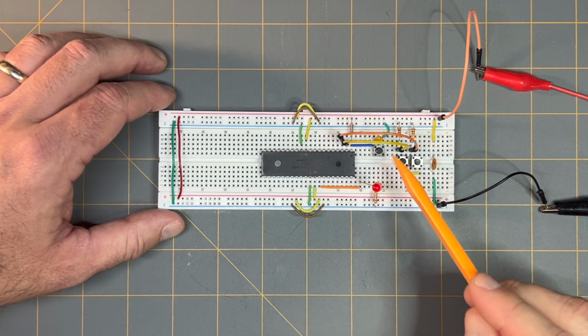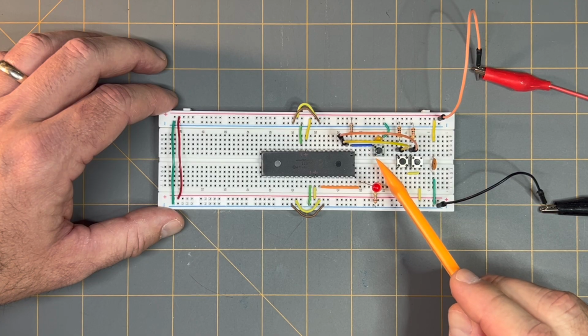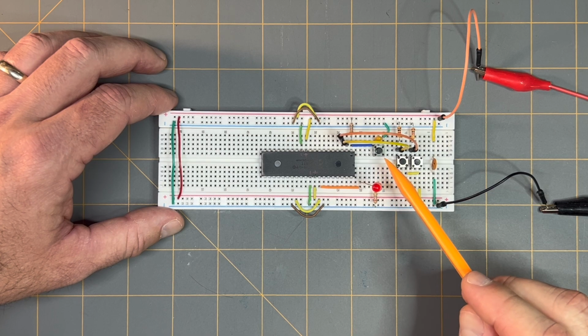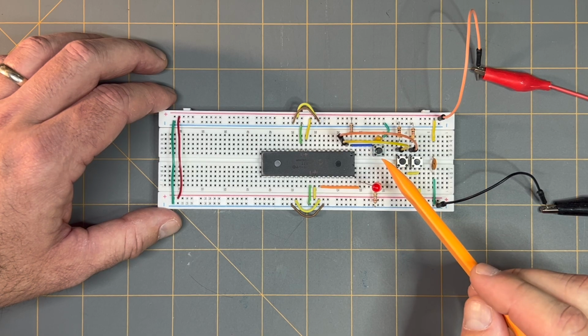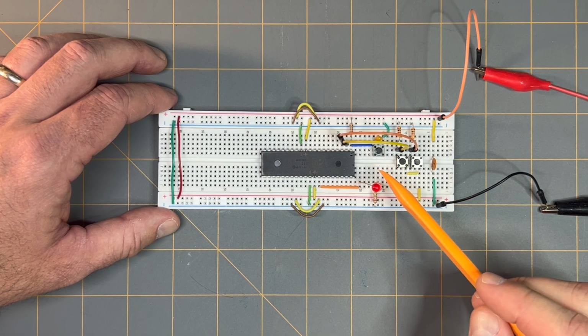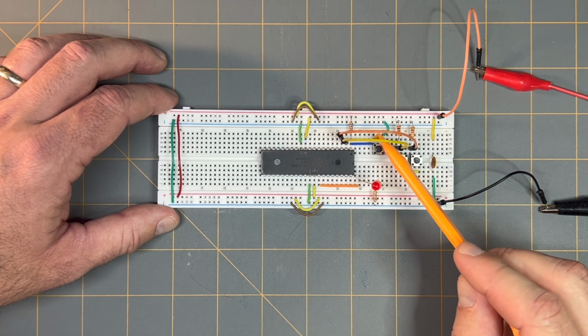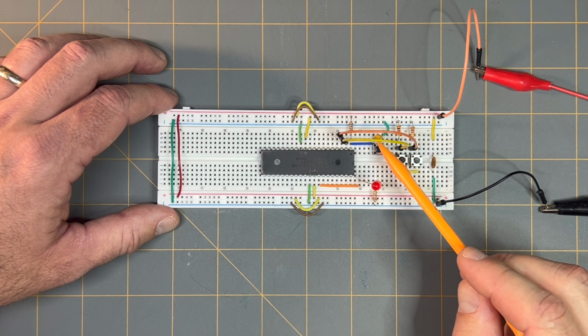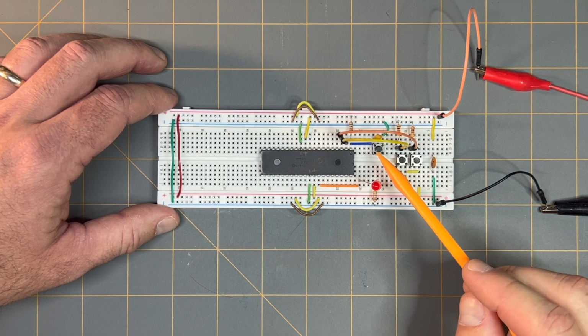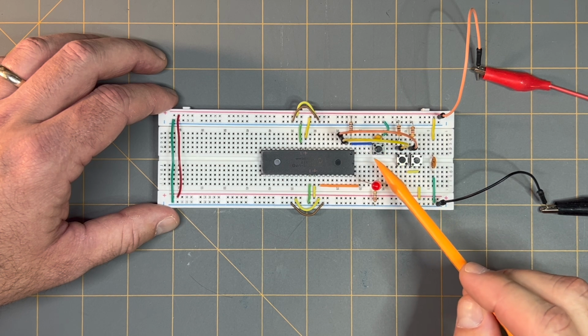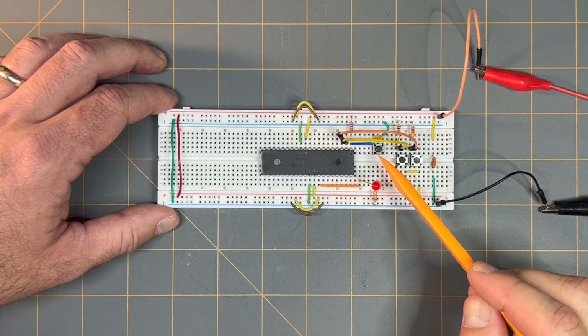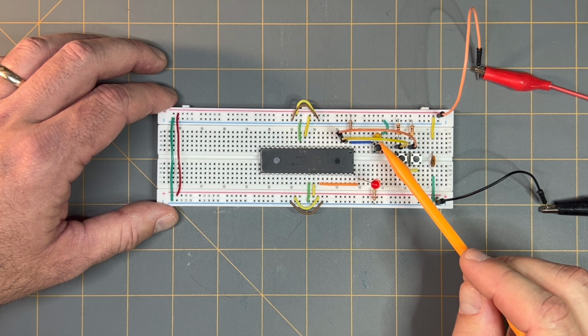Next, I took a 2-terminal momentary push button switch, and I placed one of its leads at point D17 in line with the blue jumper wire, and the opposite lead of the switch into point D15 of the breadboard. Now that the switch is in place, I took a 0.1 microfarad capacitor and placed its terminals in line with the terminals of the 2-terminal momentary push button switch we just installed on the breadboard here at points B17 and